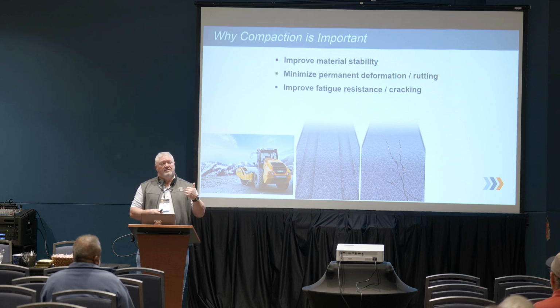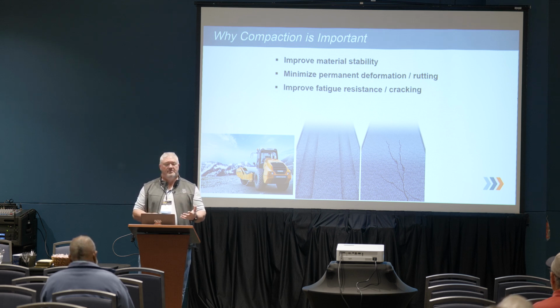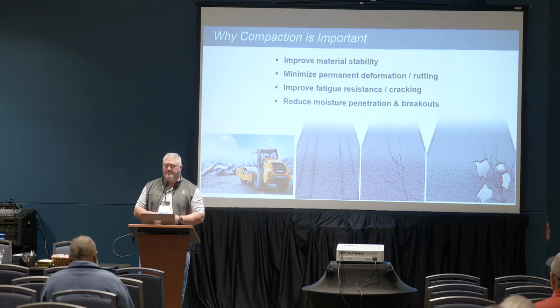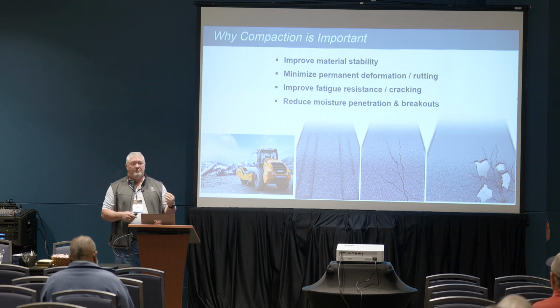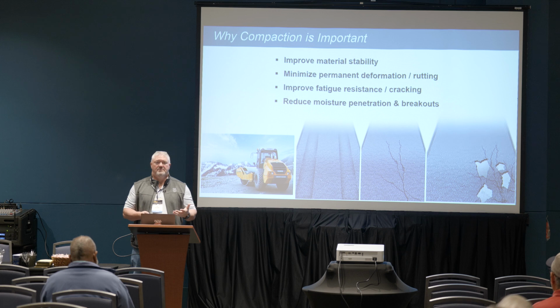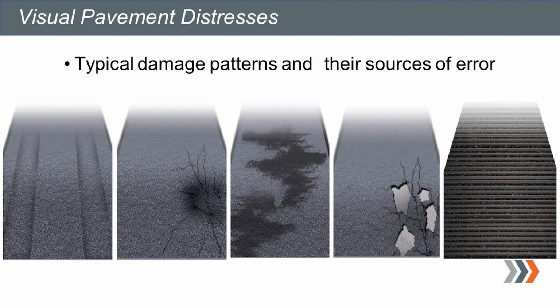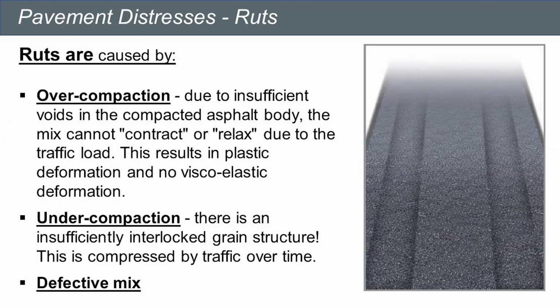If it forces the water out, it's going to take the fines with it, which has all the oil that holds things together, and it's just going to be the large stones, and things are going to ravel apart. So we want to make sure we can do that. We also want to make sure we've got correct bonding in between layers that helps us reduce any kind of potholes. So physically, when you're rolling, you can actually identify maybe some of these things based on what we're doing.